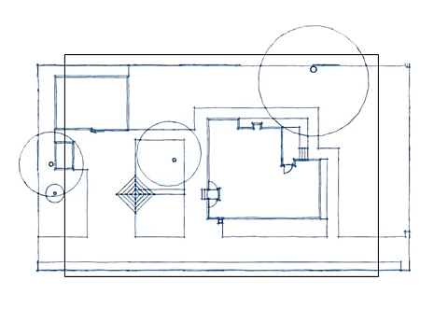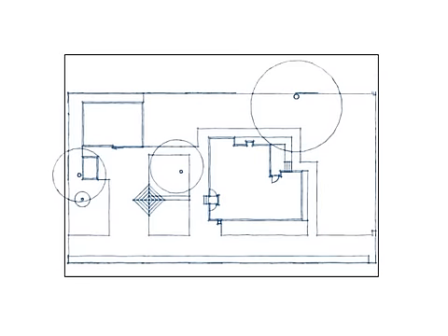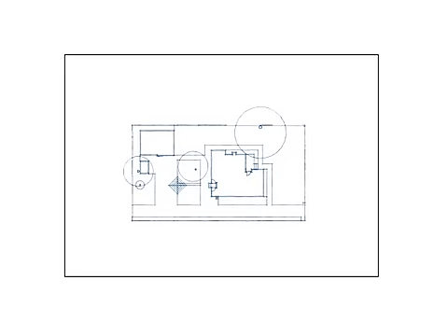Using our example section, if we drew it at a scale of 1 to 100, the drawn size of the section would be 403 millimeters by 223 millimeters. This would mean that there is only 17 millimeters, or 1.7 centimeters, of space between the drawing and the edge of the paper, probably about 8 millimeters on either side. Because we still need to draw things like labels and site dimensions, it is a better idea to draw this section at a scale of 1 to 200.